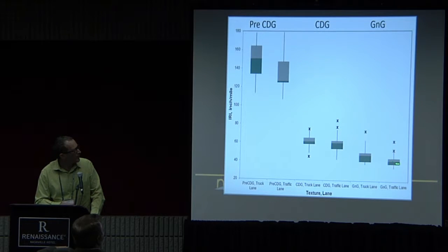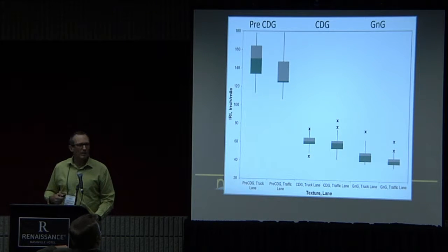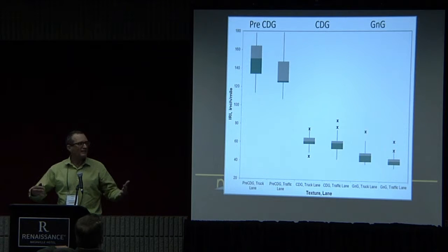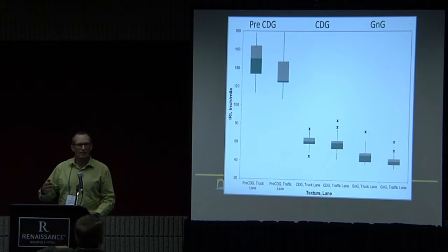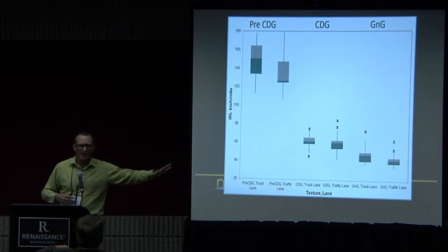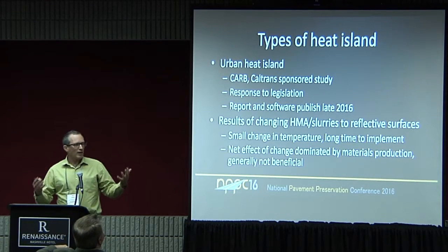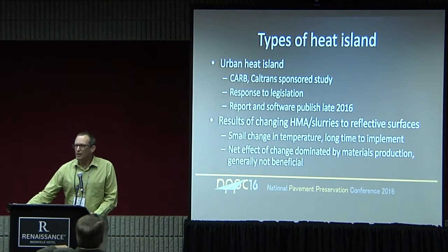But these are the smoothest pavements that we've measured of any type in California. I think we have one that's at 38 inches per mile. And with concrete, that means that inches per mile is going to stay there for a while if we have dowels. That's a whole other story for another day. Okay, so that's our noise story in a quick nutshell.